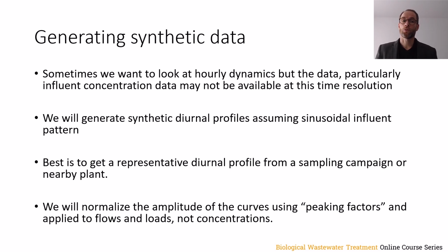Sometimes we don't just want to look at time variability on a day-to-day basis, but we also want to look at it on an hourly basis. But the data, particularly influent concentration data, may not be available at this time resolution. Most plants may be sampling the influent and measuring COD, TKN, TP, or BOD, TSS, and VSS. They may be doing it every day, but most plants don't do that every hour.